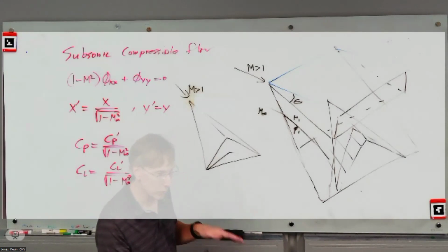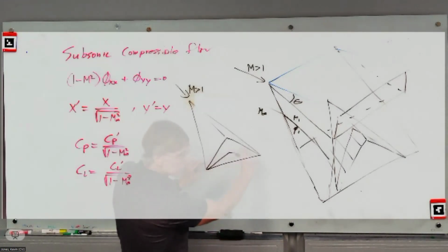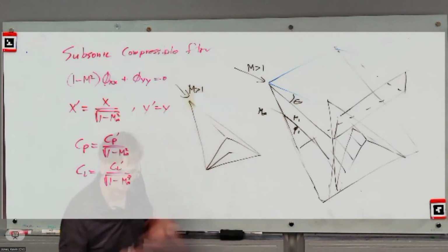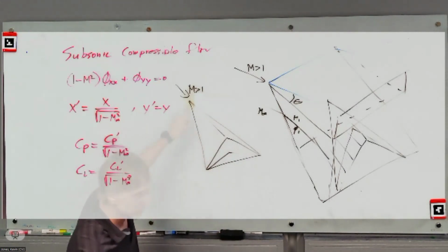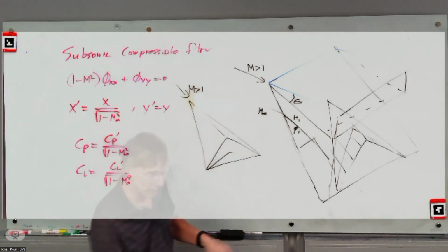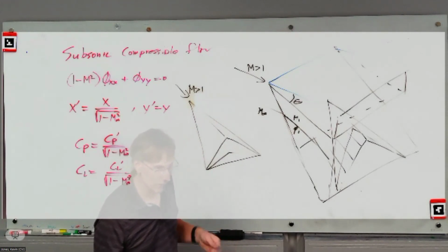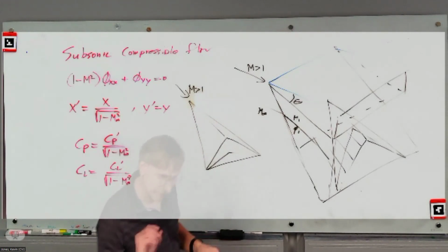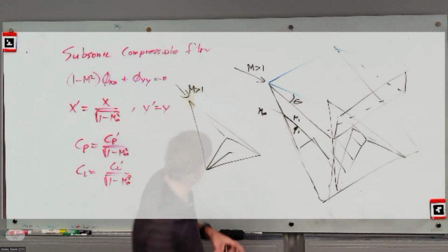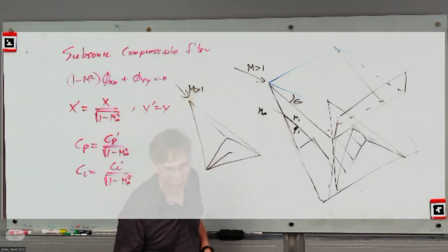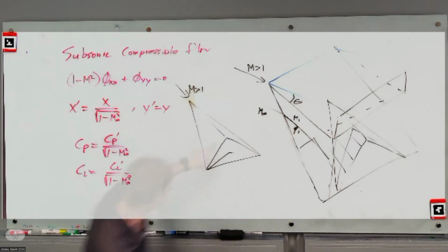And then he also took the same thickness distribution but mashed it so the top was flat. So it had the same area distribution, but a shape that was clearly not a wave rider. There's no way that shock is going to be attached to the tip of the nose. And he ran that at all different angles of attack. And it turns out the one that was mashed flat actually did just the tiniest bit better. And even the regular wave rider, the best L over D, turned out to not be at the point design. It is a point design.